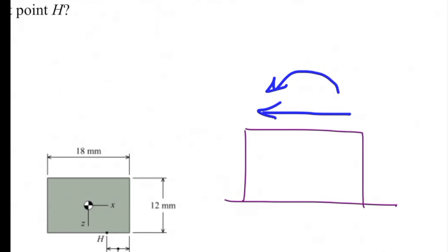What would be the effect of that shear force? What kind of stress is developed by that shear force? Shear force produces shear stress. That's it. Do you expect to see any normal stress caused by shear force? No. What kind of stress is developed because of moment? Normal stress. Does moment produce any shear stress? Now, we have these two, moment and shear force. Which surface gets the stresses produced by these two? Is it the top surface, the side surface, or the front surface?